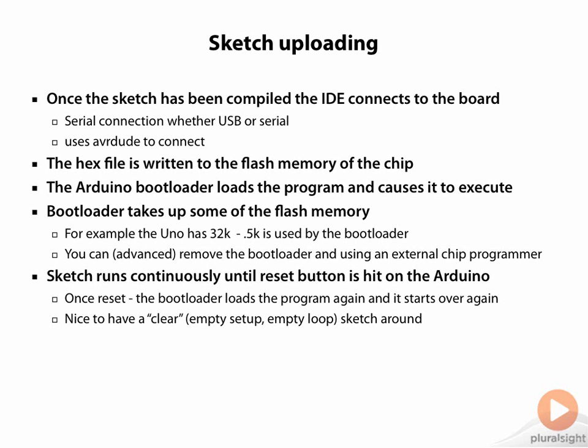As I mentioned in the demo in the first module, having sort of a clear sketch is kind of nice to be able to clear things out, just an empty setup and an empty loop. Now, is it normal for you to want to replace the bootloader and upload your sketch directly? No, but it's an advanced scenario, and if you were going to put the Arduino in a more permanent place and you did need that extra 0.5K, you could do that.